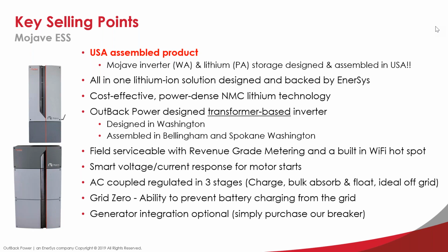The inverter unit is completely field serviceable, so I believe every board in there can be replaced in the field if necessary. So if you have a long service life planned, we got you covered there. Every inverter has its own built-in Wi-Fi hotspot. So you'll see a little antenna hanging off the side of there. That's what that's about. You don't necessarily need internet service to access the UI, because it's broadcasting that from a web server that's built into the inverter. But you'll want to have a device, a phone, tablet, laptop, whatever, with Wi-Fi, so that you can log in and see the UI.